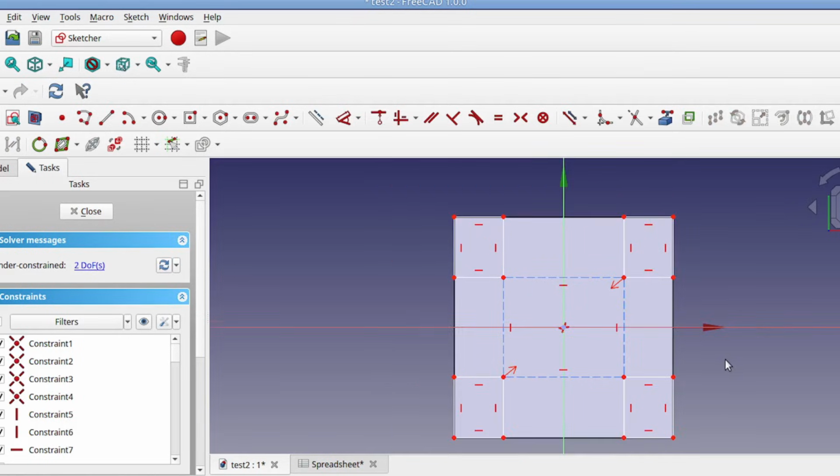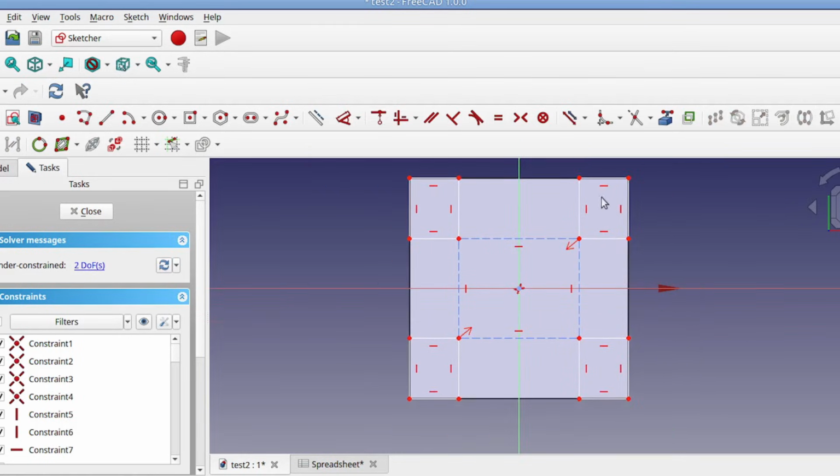And now for my dimensions, if I wanted these boxes to be 10 millimeters, I have the dimension of this big box in my spreadsheet, right? So if I want these to be 10, that's 10 for this one, 10 for this one is 20 across. So I'm going to take 20 away from my big box dimension. That's how I'm going to arrive at the distance between these 2, or the dimension I want to set for this construction line. So I'll select that.